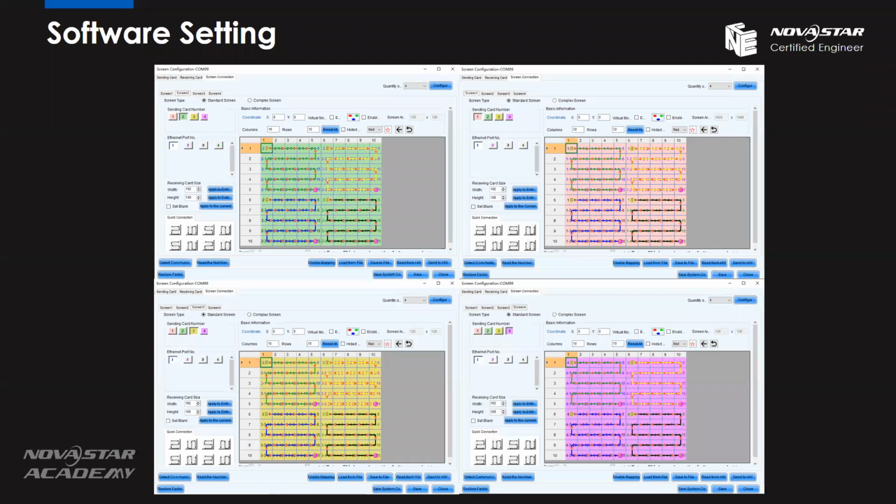But you may be wondering, in the previous structure with M-Control 660, we did not set the image offset. The reason is we have a video splicer which can do this job. But now we do not have a 4K video splicer in the front. So why do we still not set the image coordinates? Don't forget the VX4S is an all-in-one controller. It's a sending card and it's also a video processor. So it can also do the video processing functions, because the VX4S or the Pro HD has a function named image mosaic. The image mosaic will help you splice several sending cards to load a big screen.